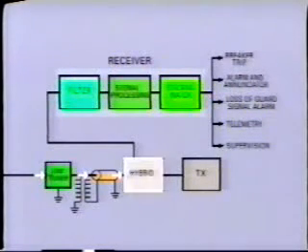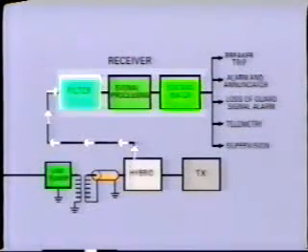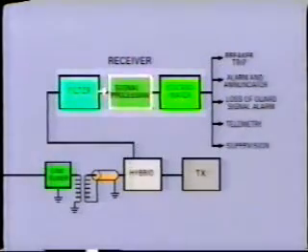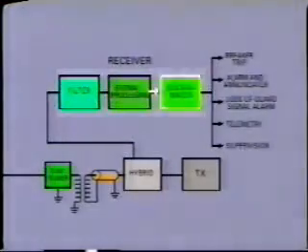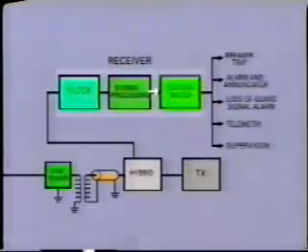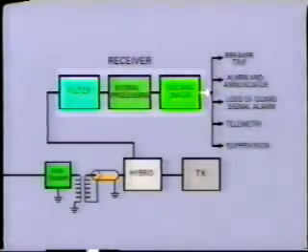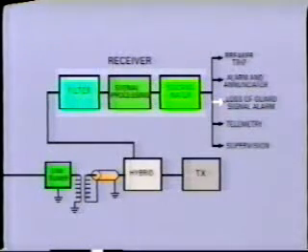The receiver equipment is similar. First, the incoming signal passes through the hybrid, then the input filter. The signal may then be processed and fed into a discriminator or other similar device which recognizes the message and triggers action, such as breaker trip, alarm and annunciation, loss of guard signal alarm, telemetry, supervisory control. Of course, we're looking here at a very basic arrangement. Your carrier equipment will consist of many more modules, components, and facilities for monitoring and adjustment.